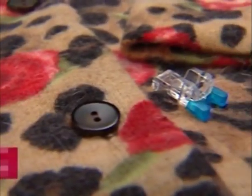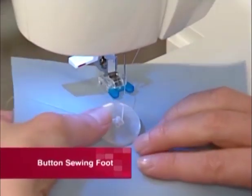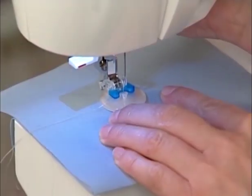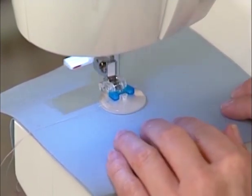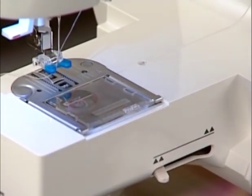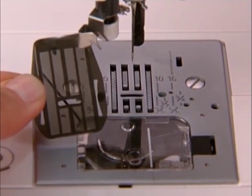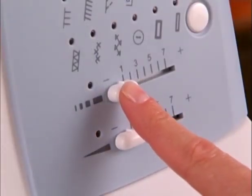The button sewing foot is used to easily attach buttons, whether they are 2-hole or 4-hole buttons. It holds the button securely in place while a zigzag stitch is used to attach the button. If the machine has a drop feed lever, lower the feed dogs. If the machine does not have a drop feed lever, then place a feed dog cover plate over the feed dogs or simply set the stitch length to 0.